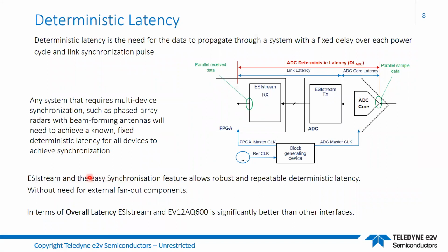EasyStream and the easy synchronization feature allows a robust and repeatable deterministic latency without the need for external fan-out components that you get with existing systems using LVDS interface, and also JESD204, which requires an additional fan-out for the SYSREF function as well.